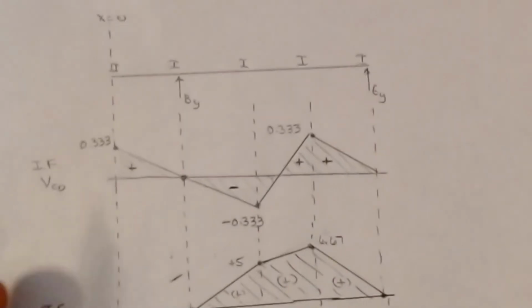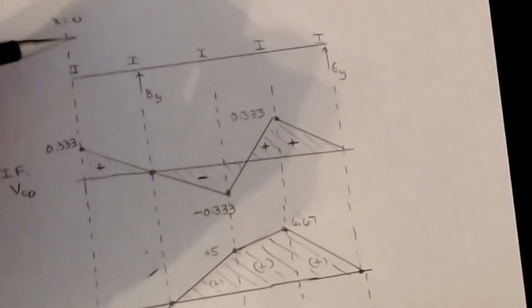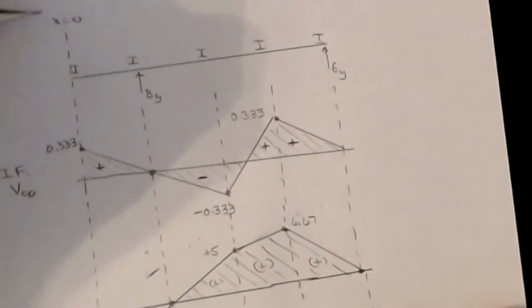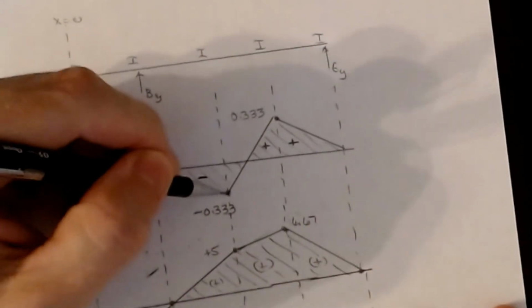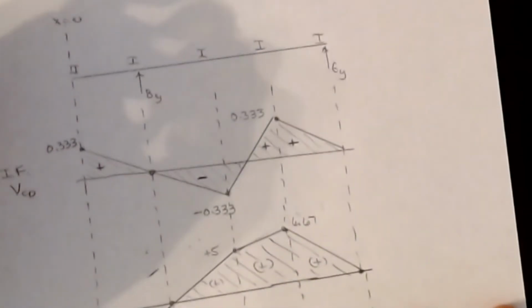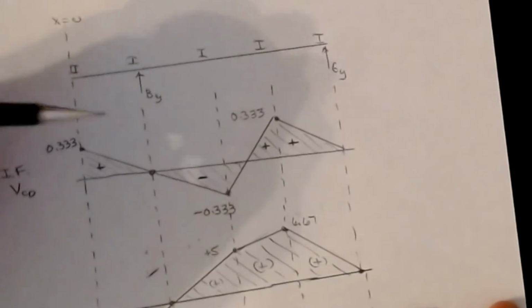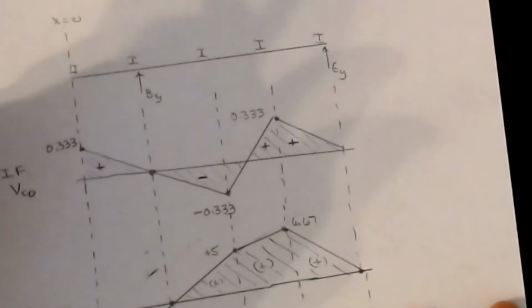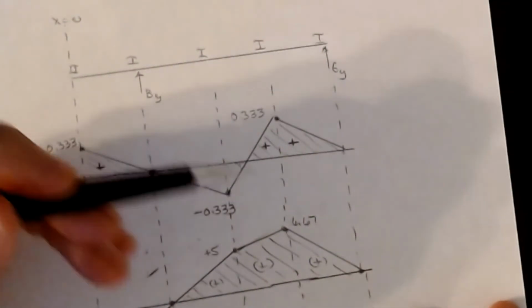Okay, and so this is what we get. So here's my beam. Okay, and again, I'm not drawing the panels or the load on this thing, but what happens is that one kip load moves across those panels. If I plot my points, I got a positive 0.333 here, a 0 here, minus 0.33 here, and plus 0.33 here. And then of course 0 out at the end. And so that's the shear diagram for this load as it moves across the panels. Like I say, it doesn't have the jump that you saw in shear before because the loads are being spread out and coming into the location of interest in different ways. But it's just simply a math problem and then plotting the functions.